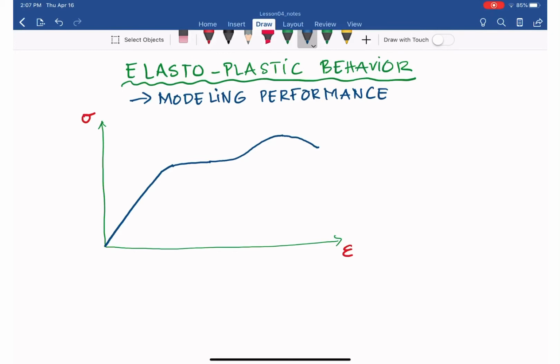Now when we model with the elastoplastic behavior of the material, shown in the red line, during the elastic phase we model exactly the same as the real curve of epsilon and sigma. Then when it goes to yielding in the plastic region, we just assume it is horizontal. So it's purely elastic in the first phase, and then perfectly plastic in the second phase.